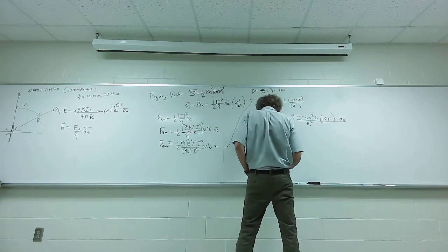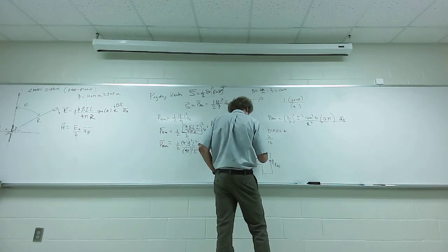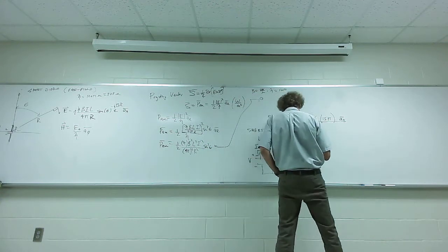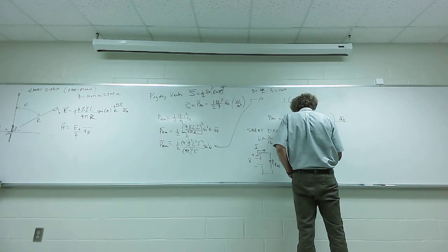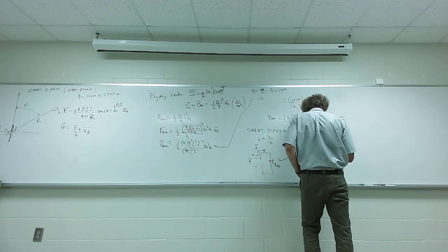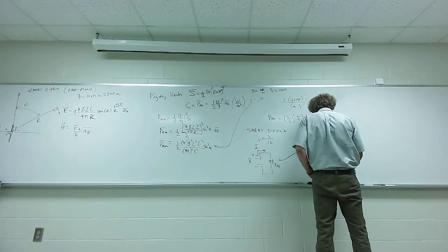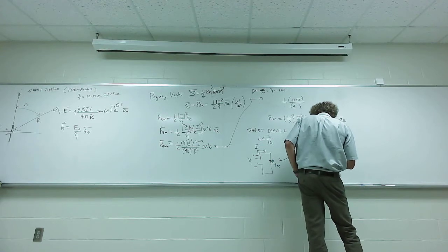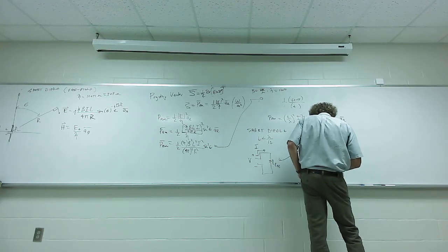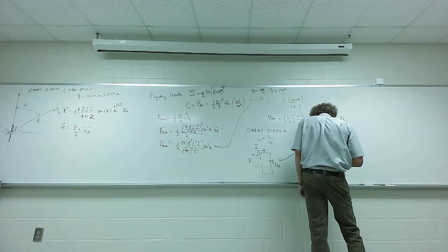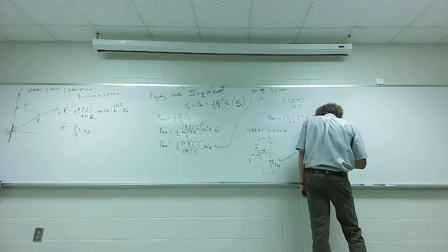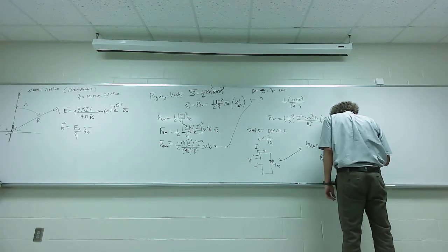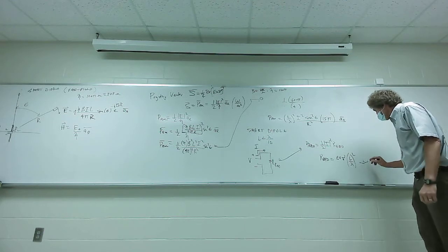As such, we can say the total radiated power from this is equal to 1/2 the magnitude of I squared times R rad. The radiation resistance, and this is for the short dipole, is equal to 80 pi squared (L over lambda) squared, and it's usually small. The units of this are ohms.